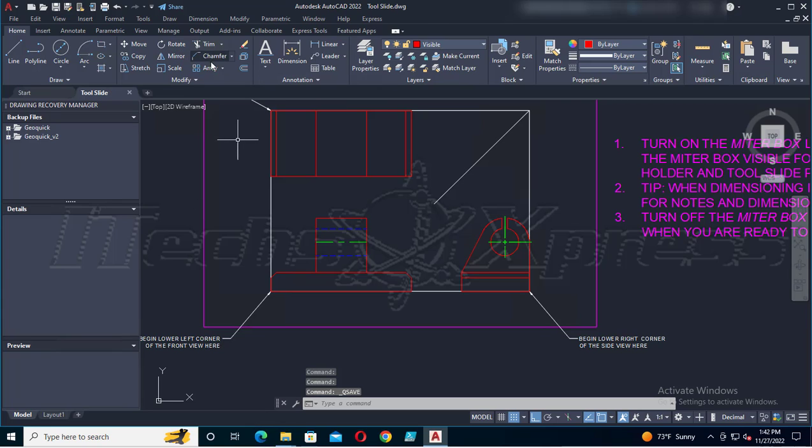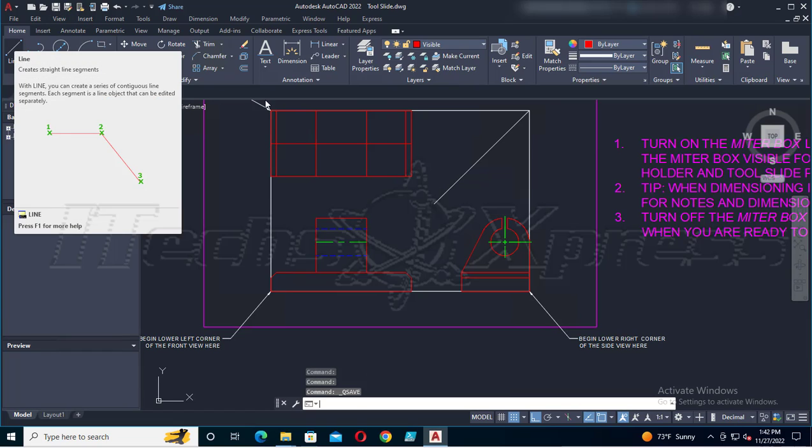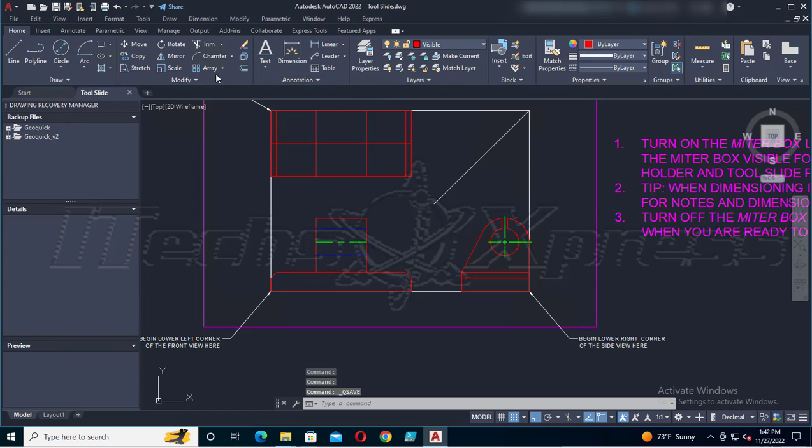Alright, so now it's broken apart, I can offset. Where's my offset command? There it is. Offset, I think I'm going to go 1.5. This one up, perfect. And then I can repeat the offset command. Here, I'll do 1, click on this line, and go there. Perfect. And this should give me the center of this circle here.